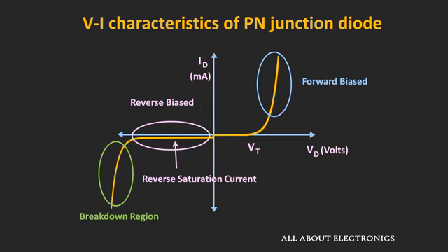So this effect is known as the avalanche breakdown effect, and the voltage after which it occurs is known as the breakdown voltage. So far we have seen that this avalanche breakdown effect is caused by impact ionization, meaning that a high energy charged particle can knock out the bound electron from the silicon atom, and in this way it creates an electron hole pair.